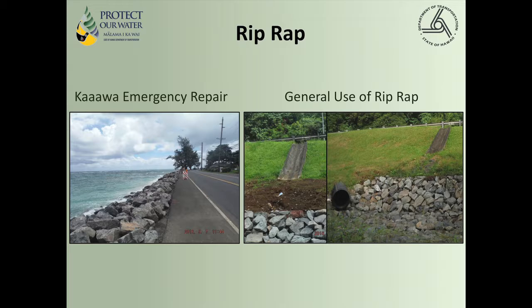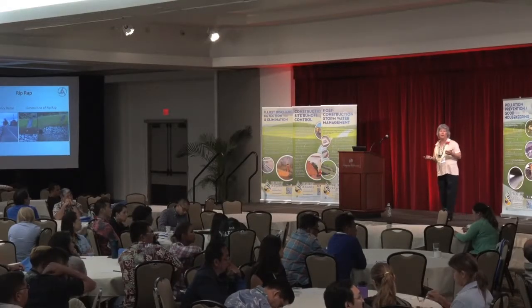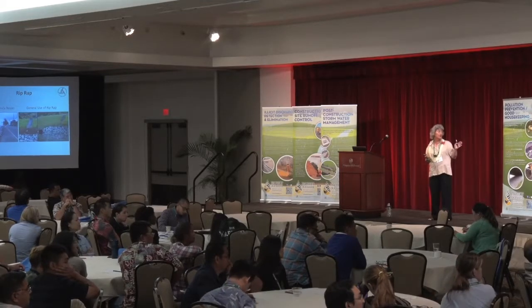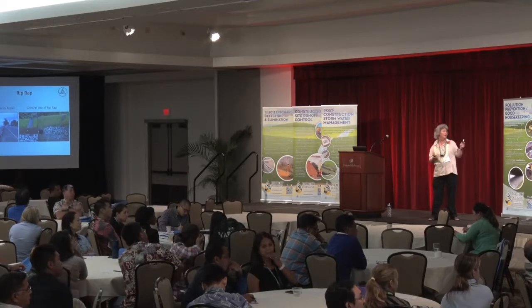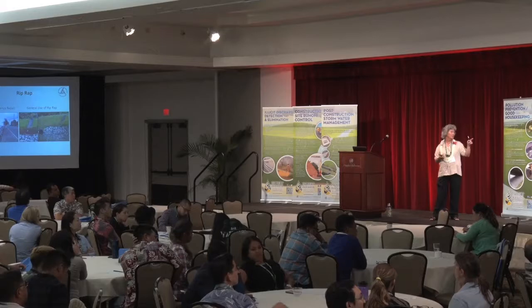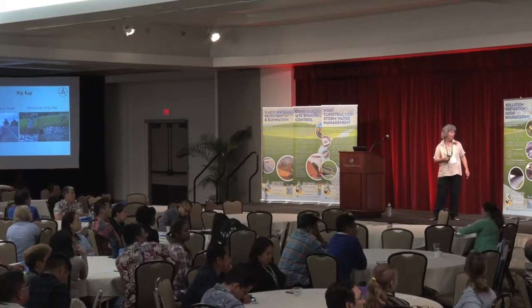The two in the middle and the right show two things. Use of general riprap at the outlet, and also why vegetation is important. Before they remat it at the end of that concrete swale, it was starting to erode out. Once grass grew, it held.